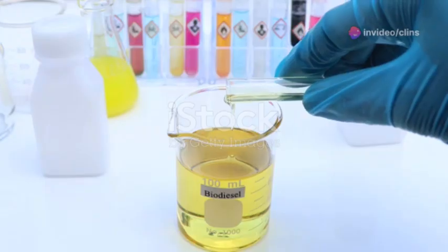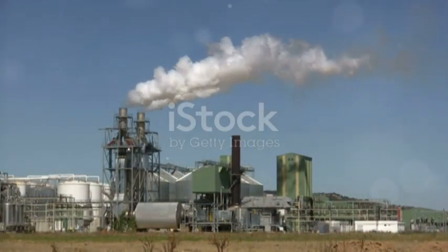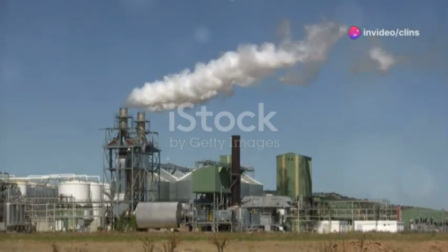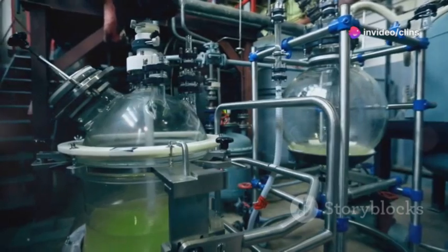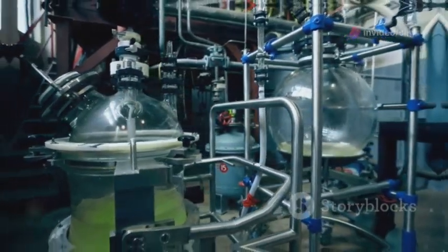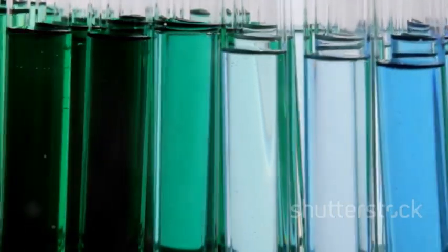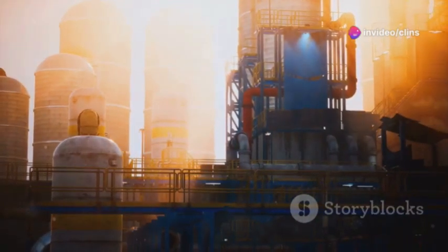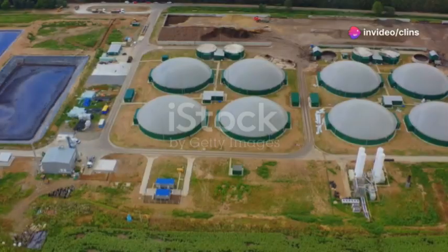All right, let's dive into liquefaction. The principle behind this method is converting biomass into liquid biofuels at moderate temperatures and high pressures. The process involves mixing biomass with water and subjecting it to high temperatures and pressures in a liquefaction reactor. This results in the production of biocrude, which can then be further refined into biofuels. The applications? Well, it's mainly used for producing liquid biofuels like biodiesel and biooil.